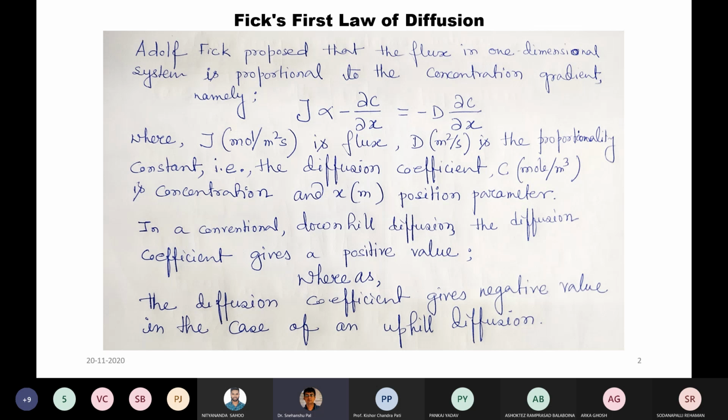If you take an example, suppose an inhomogeneous single phase alloy is annealed, the mass will flow in a manner which will decrease the concentration gradients. Now what is annealing? From the materials engineering perspective, annealing is heating a metal sample to a certain high temperature and then performing furnace cooling. I mean, you keep the sample in the furnace itself, switch off the furnace, and the furnace slowly cools down, and the material also cools down. So that is a slow cooling process, and it leads to a scenario where the specimen gets rid of residual stress, or the residual stress is reduced. This is the main objective of performing annealing.